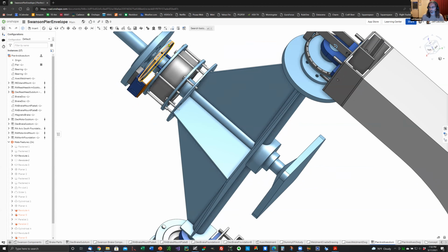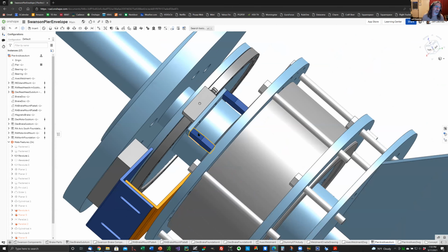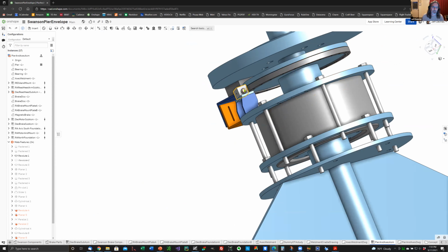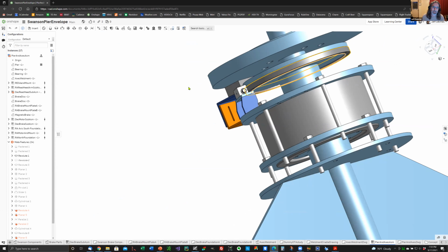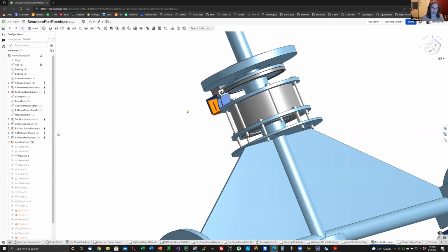These encoders are absolute, and they are extremely high precision. The way they work is the outer band of this has a type of barcode on it all the way around, and then the read head for the encoder is actually a little camera. It's a little optical reader, so it just looks at that barcode, and it can tell absolutely what position the telescope is in, one for each axis.